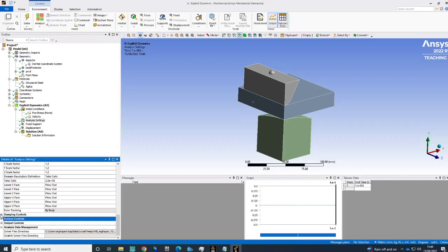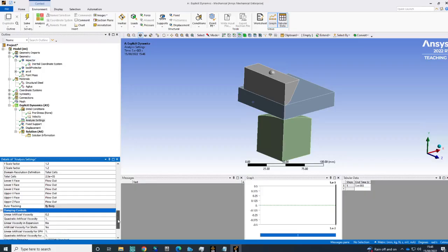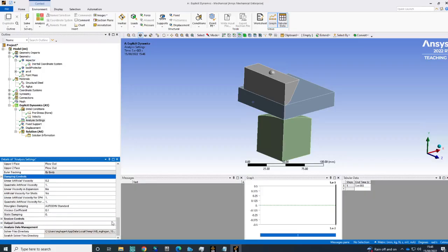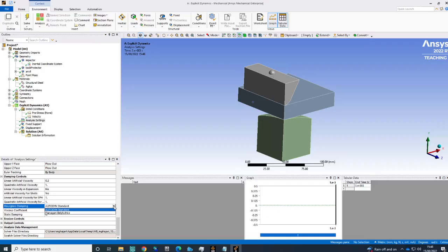And you can see here, for instance, under damping. Damping is usually used to deal with hourglass energies. The default in Elastina is using reduced integration, hexahedral elements. Therefore, this damping is being used, and specifically hourglass damping is being used here, and there are two types.